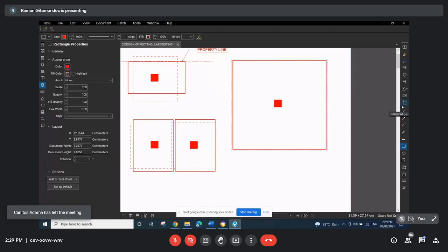So it might be thin. If the footing is very stiff, it will behave more as a rigid foundation, and I think even distribution of the reinforcement is okay, no. But for relatively thin footing, you have to consider the footing and soil interaction, no. So if your footing is large and thin, of course the bending moment will be larger near the column when compared to the strips farther from the column, no?